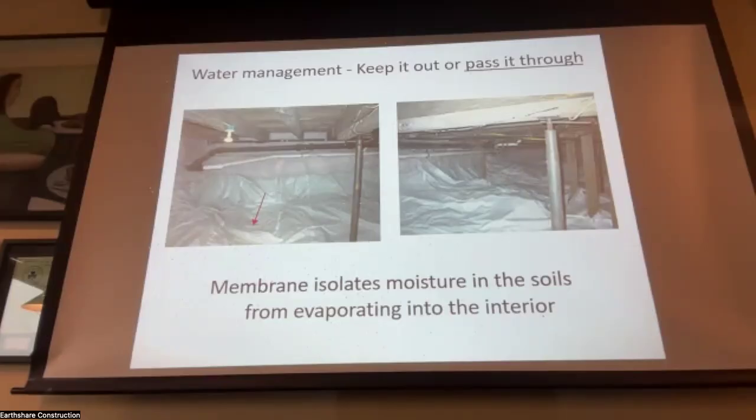With the Too Tough, do you have to mechanically fasten it, or do you just roll it out? We use, if you do gardening, they make U-shaped fasteners to hold your landscape fabric down. Staples. Yeah, and that's what we used. We held it down to keep it in place while we moved around on top of it. And if you have a low spot, poke a hole. Yes, assuming what's under it is going to absorb the water. If what's under it is ledge, then you want it to run down on top and then get to a hole at the sump.